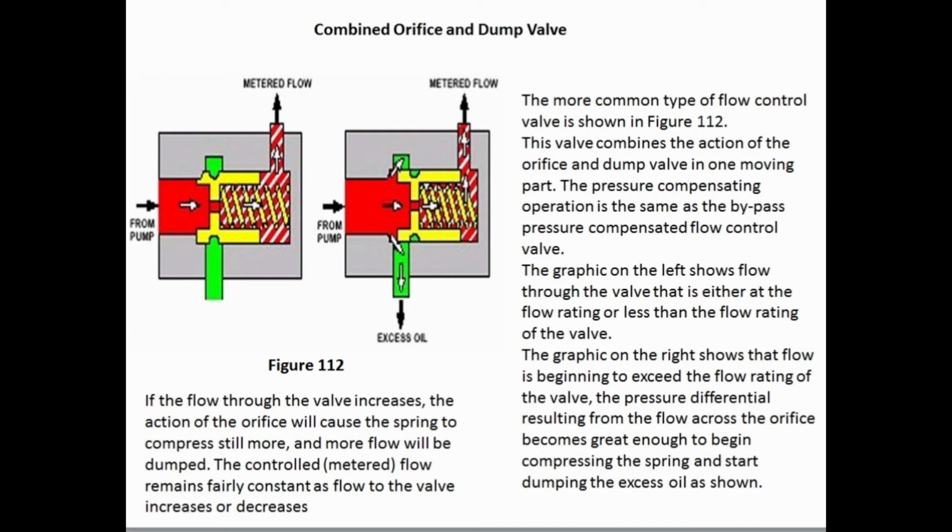If the flow through the valve increases, the action of the orifice will cause the spring to compress still more, and more flow will be dumped. The controlled, metered flow remains fairly constant as flow to the valve increases or decreases.